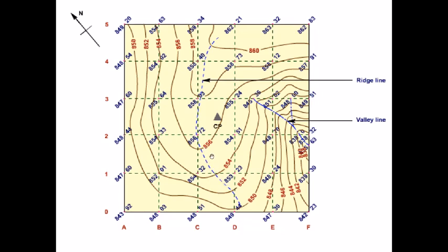So whenever you get a shape like this, that means it's a ridge line. And we discussed before what is a ridge line. A ridge line is the top of a mountain peak, or it is in continuation in this case. So you have a peak that has a decreasing elevation as you move down, but if you're standing at the top and you keep walking in this direction, the elevation would keep on increasing in a straight line.